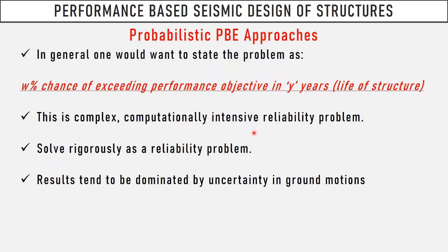And additionally, the results are more dominated by the uncertainty of the earthquake input. This means that you should involve more ground motion input sets and provide more reliable solutions. But of course, this time you come up with high analysis procedures, high analysis tasks.